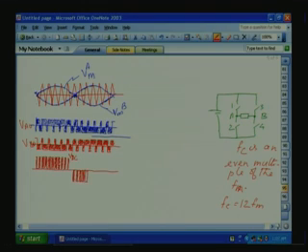So this variation is also sinusoidal, and the fundamental of this one will be 2 times the modulating wave for A. Because the fundamentals of VA0 and VB0 are 180-degree phase shifted, when you subtract, both will get added. So we will get an increased fundamental here.